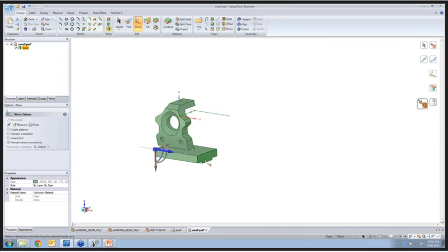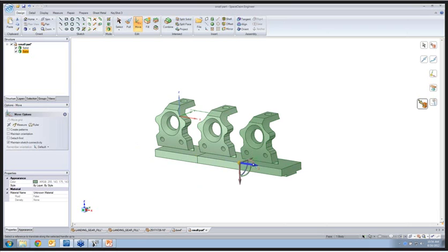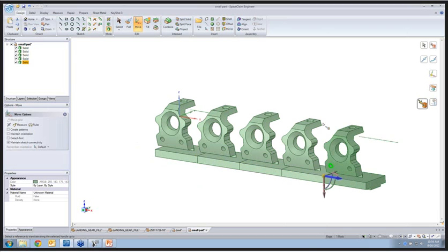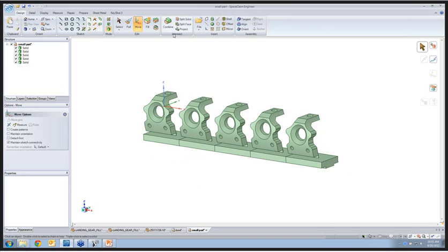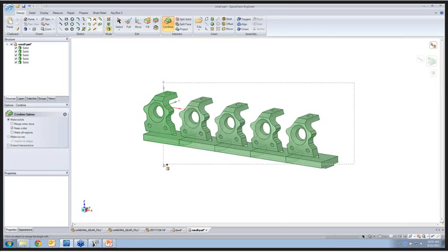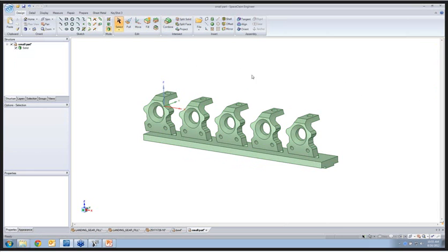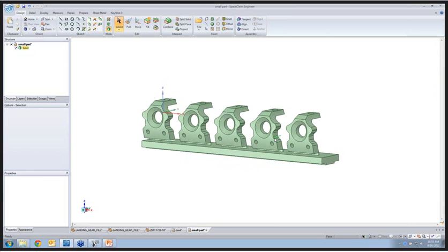When you're in Windows and you move files, everybody understands that. But if you hold down the Control key and you move files, you make copies of them. And it's no different here. When I Control-click, I'm making copies of all instances of those solids. And all 5 of them are put together. They're separate right now. They're not connected. You can see the lines in between them. But hey, I just used the Combine tool and merged them together into one. Okay? So I've got 5 parts.